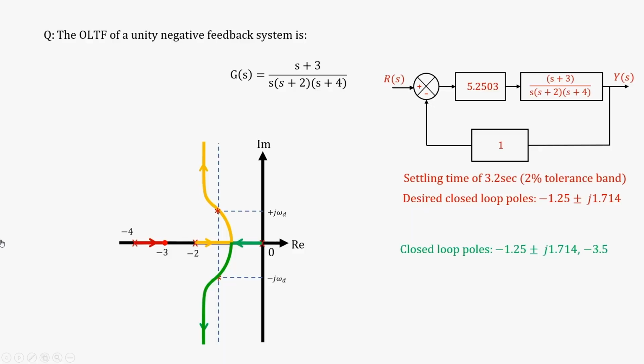the settling time, but you can always design it for 4.5 seconds, okay, and then see whether after designing, because of the effect of the poles, the third pole and the zeros, you can reach that exact point. So, this is how you can reiterate as well. You can change the design parameters a bit and try to get to the exact point. Okay. So, what is happening here again?